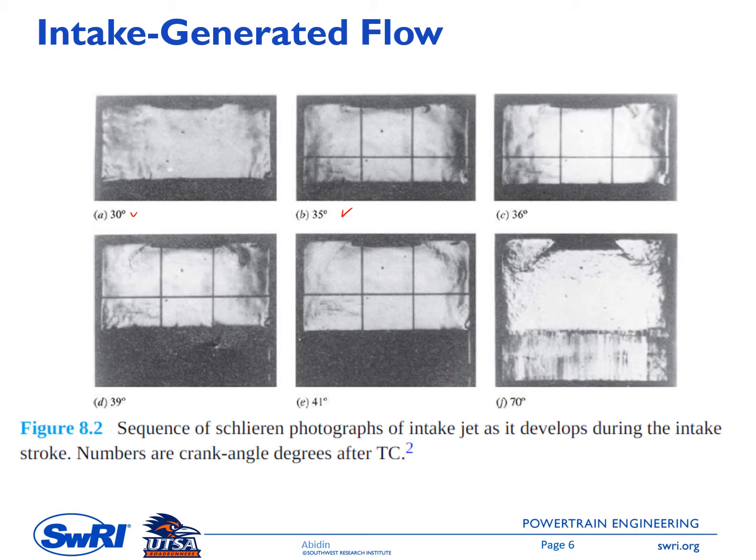You can see that this engine, I think, has one single valve, and it is at the center. This is the intake valve. Then you can see the flow pattern, although it's not so clear on this one. As the valve opens, you will see a clearer flow pattern here. In this one, you see that high flow is entering the chamber, hits the liner, and is then deflected to the center of the chamber.